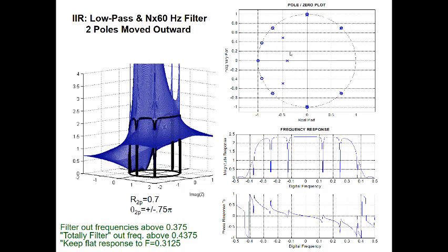Now, that's not to say this is the only way that we have to design digital filters. There's actually a number of deterministic ways. There's several techniques for designing FIR and IIR filters that we can target certain design requirements, build that into our design, run it through the process, and get what we were asking for. This particular filter is kind of a combination of different kinds of filters, and using this pole zero technique, it's again much more qualitative, much more seat of the pants, not as deterministic. So we keep having to tweak it until we have something that's usable.